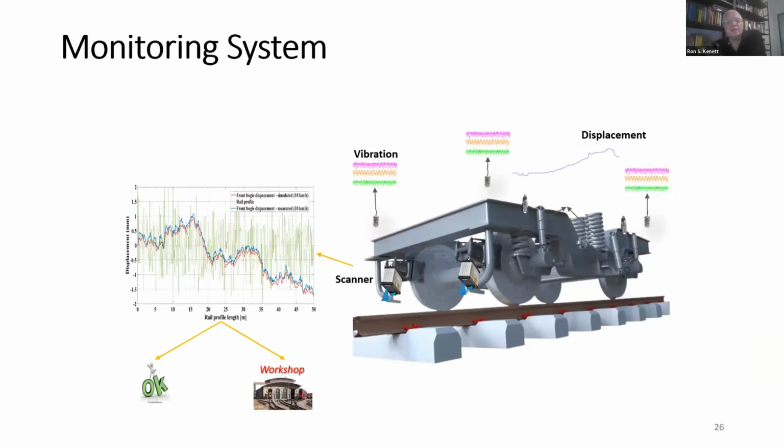Through the sensors, we have a picture that gives us a comparison of what is supposed to happen and what is happening. If what is happening is matching what is supposed to happen, we are okay. If there is a gap, that's when the system has to be looked at, and the prognostic model will tell us if this is urgent, it's a showstopper, or this can be looked at when the train gets to the station, or maybe during a monthly or weekly checkup schedule.